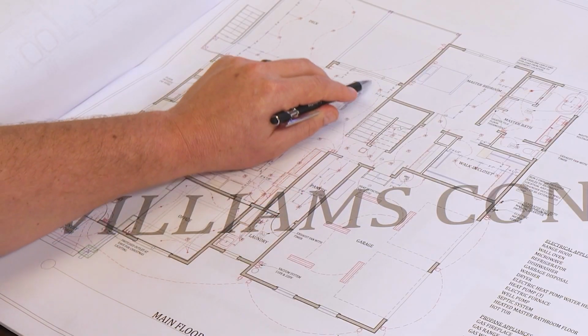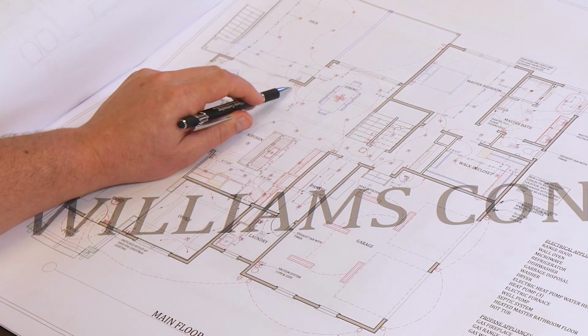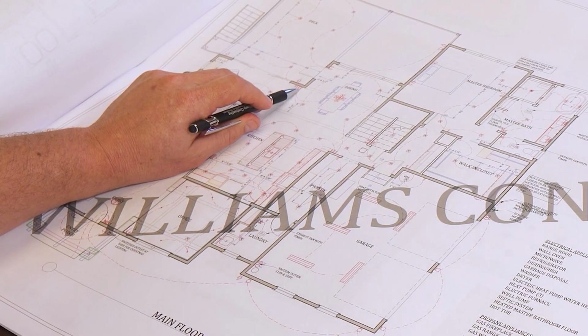We do have some 3-ways. Right here, this switch light controls these main dining room lights, but it's also controlled over here by the exterior doors. Paying attention to your electrical plan, both in light location and special outlet location, is really important. This is one of the most interactive times in a build. We bring the owners on site, we walk through the house with the electrician. Electricians start doing their box layout.